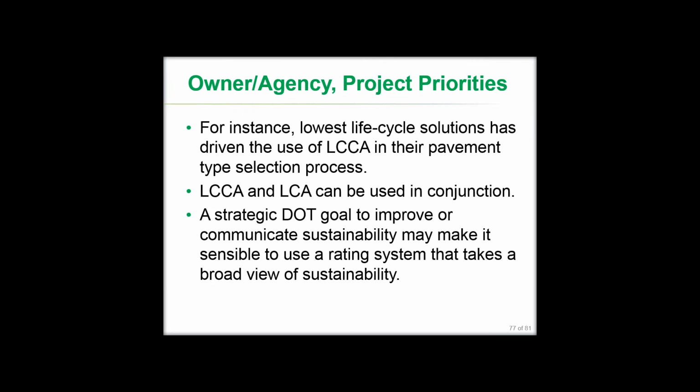Now, there are different examples. Lots of DOTs are already working on looking at lowest lifecycle cost solutions, using LCCA in the pavement type selection process, using LCCA during the early design process to optimize for cost. A lot of information, and that's the beauty of what goes into an LCCA, can be recycled in a life cycle assessment. If you're collecting the cost data for pay items and materials and processes for the life cycle of the pavement, that's information you also need for life cycle assessment.